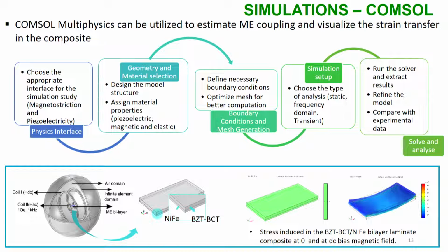One is the magnetoelectric problem, another is the piezoelectric problem, and the third one is the interface problem. So, these three problems have to be put together. Here, all the material properties have to be put in properly. Once again, any mistake or variation in the material properties will also affect your results. So, it is not that this gives you only an indication.